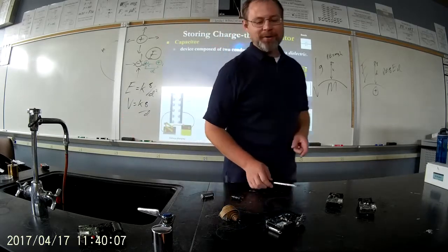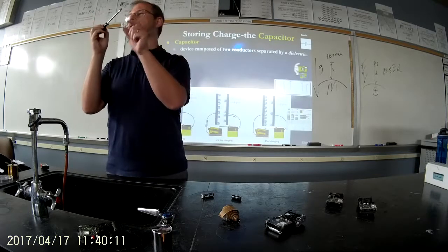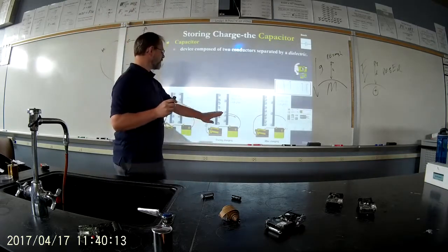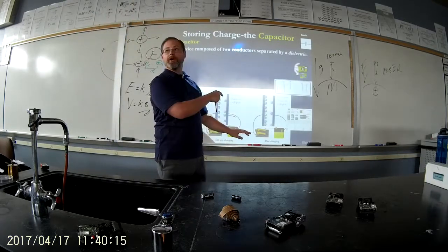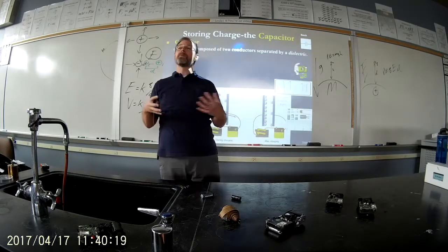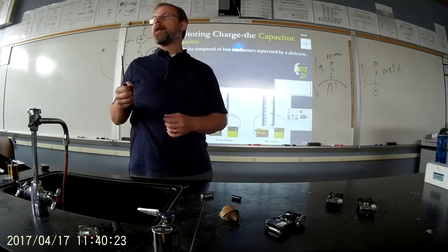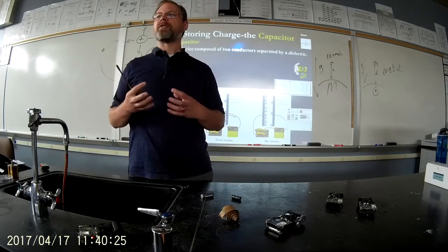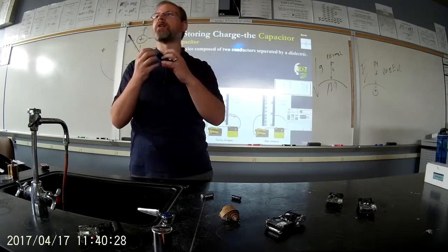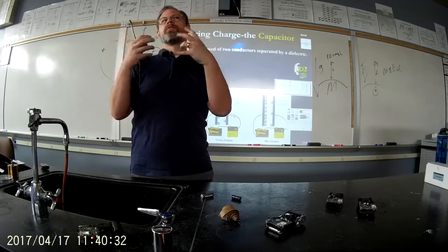So let me tell you what's going on. When I bring the screwdriver to the poles of the capacitor, I now give the capacitor's charges somewhere to go. I allow the negatives to go over, or the positives. I basically allow the charges to move and neutralize. And what you're seeing is superheated metal. The sparks are superheated metal, because electricity is traveling so fast, the metal is torn away from its neighboring atoms.